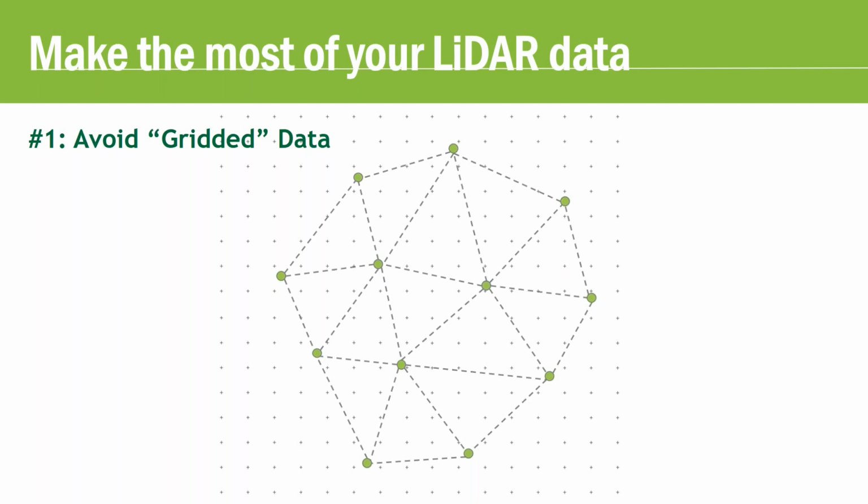The first is to avoid gridded data. The key point is basically around the fact that you're not getting any new information. You're just adding a ton of incremental points. So don't use pre-processed data, avoid gridded data, and just use your raw LiDAR file.